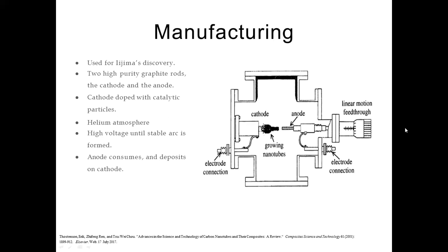This is the system that we looked at initially and is used in quite a few of the carbon derivative applications. This is the arc discharge method, where we actually arc the material from the anode side, and then we collect our growth species on the cathode. So this is the manufacturing method, and we can see on the far right, we apply the arc distance through that micrometer on the side, and we can also control the ambient inside the machine, which is usually helium, and we can also control the pressure and certainly the arc energy along with the distance.